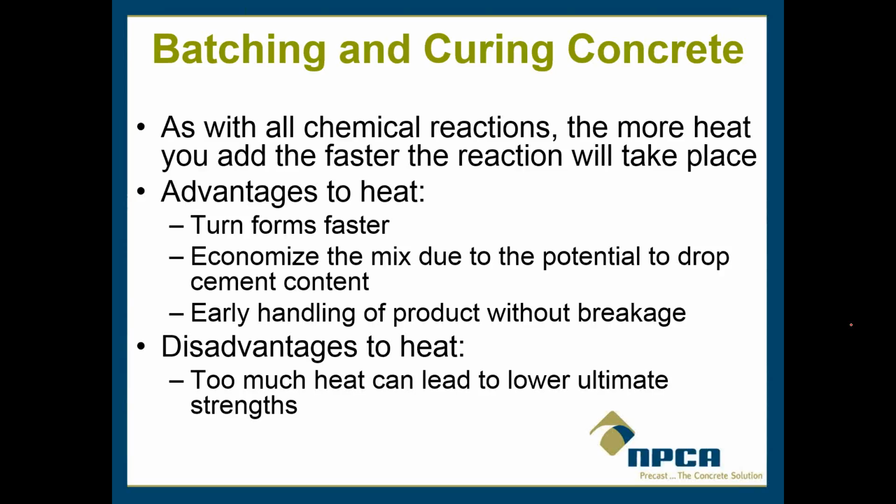So onto the slide that we're on now, advantages to heat. You can cure things a little bit faster. You can handle the product a little bit earlier, hopefully without breaking, as long as you're not throwing things around, and good luck throwing them because they're really heavy. But you get what I mean. Disadvantages to heat. Too much heat could potentially lead to lower ultimate strength if the reactions occur too quickly and the cement all doesn't get a chance to hydrate.